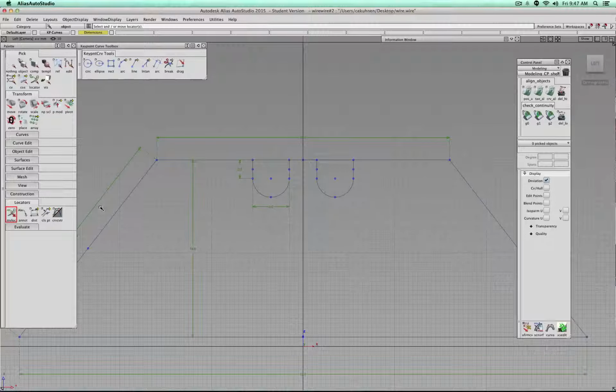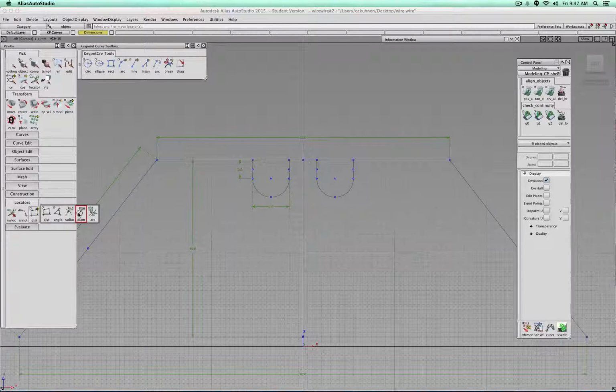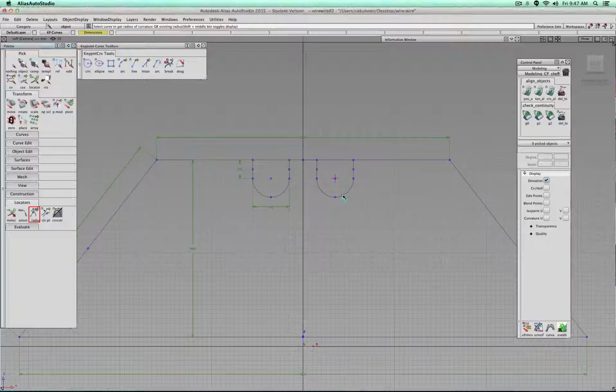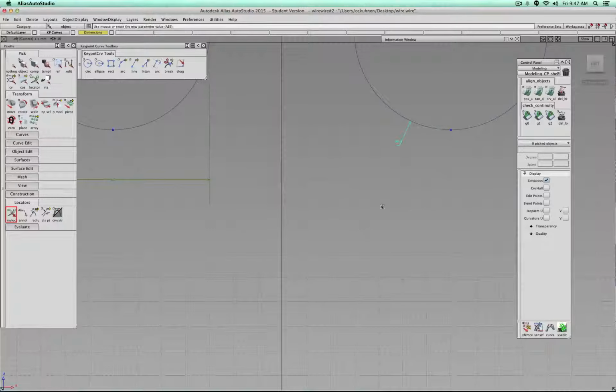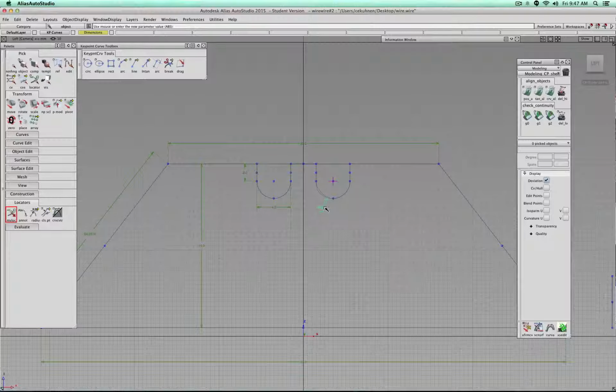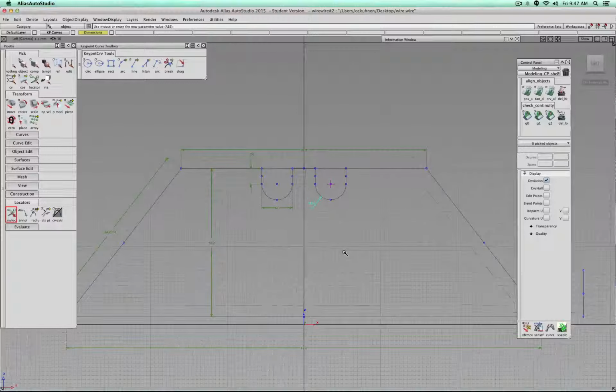And for example, if I want to, let's put in a radius. We can't use a diameter because this is an arc, so we need radius. So you click, you can rotate it, go to locator, you can rotate it, and if you zoom in and you click on this line, then actually you can extend it. If you click on the arrow, you can move it. Maybe make this one a little bit even so it's not too chaotic.